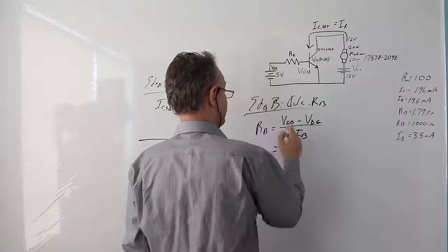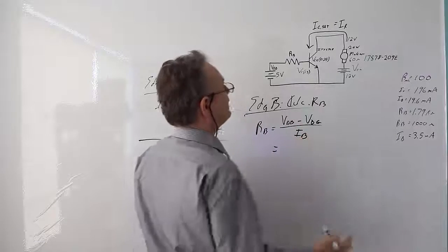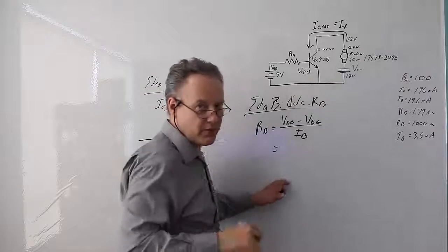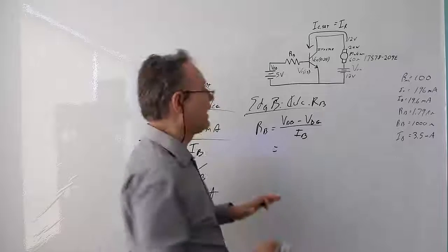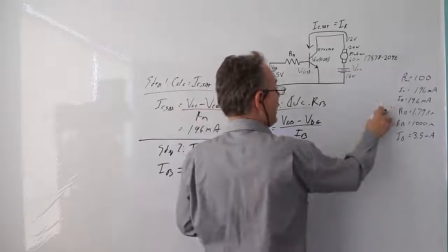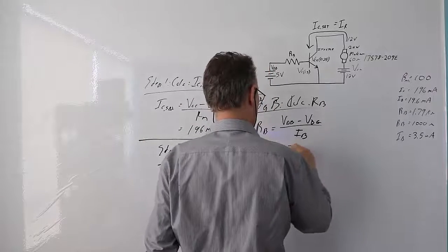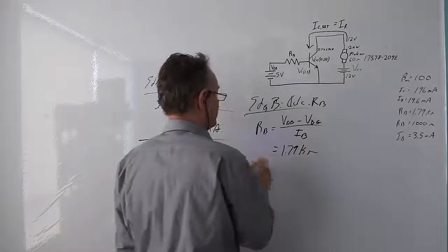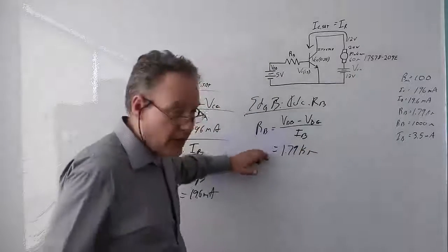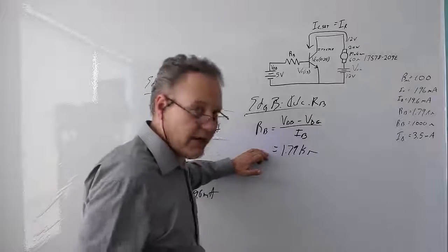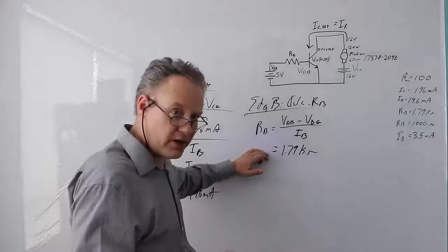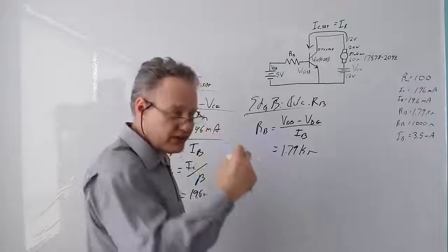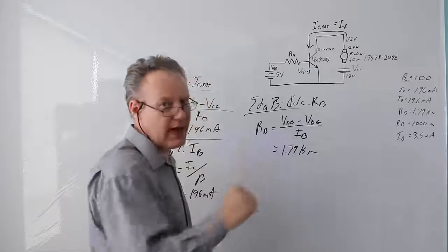So in this case, this guy over here, well, I've calculated, although that's actually 1.2, but I calculated for 1.5, but we're going to roll with that. So that guy is 1.79 kilo ohms. Cool. So if I actually had a resistor at that exact value, I would have the exact amount of current, just barely, just to saturate it exactly.